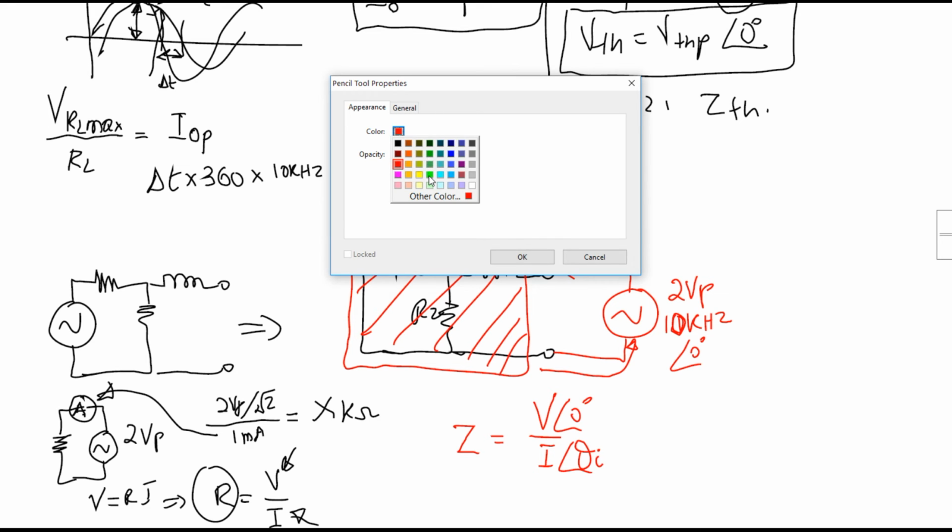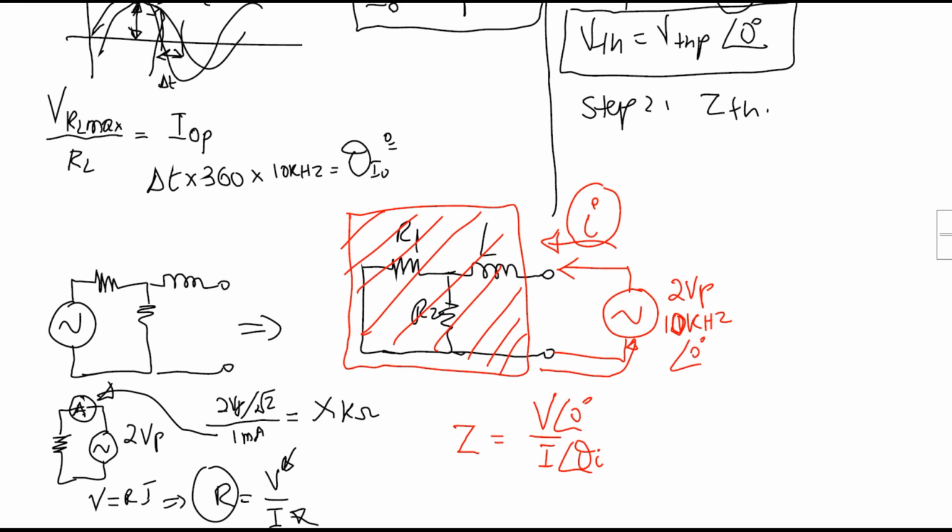for our case, we are using this Tektronix. So what you have to do is add a resistor here in series, in this section exactly. Since our probes should be grounded, we use the resistor in this section, in the return of that current. The value of this resistor should be selected so as not to affect the internal resistance of this box. So it's better to make it very small, can be 10, can be 50 ohm, for example.